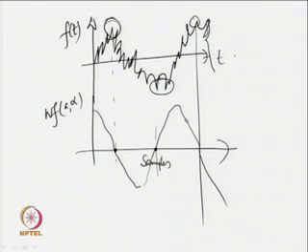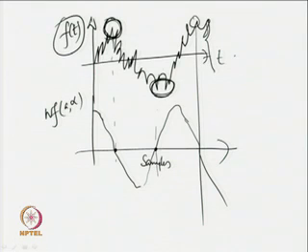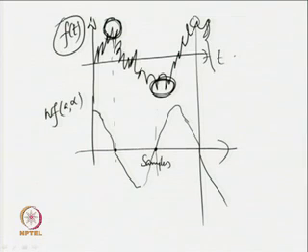So, actually the form or nature of this wavelet transform plot is not important. What is very important for us is that the extremum of the signal is tracked accurately by the wavelet transform technique. So, using the wavelet transform, the peaks of the corrupted signal can accurately be found. How can you find them? As I have done here. The peaks result in 0 values, therefore, we can accurately find the 0 crossings.